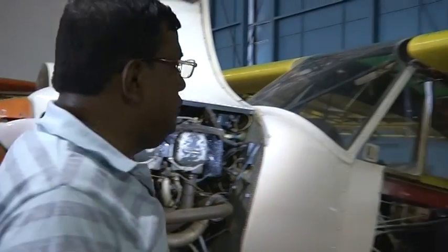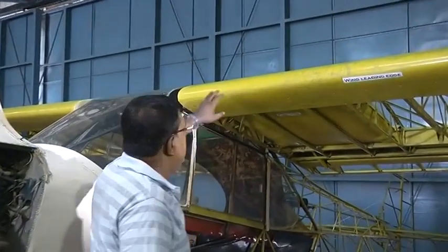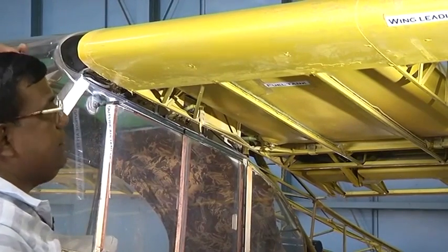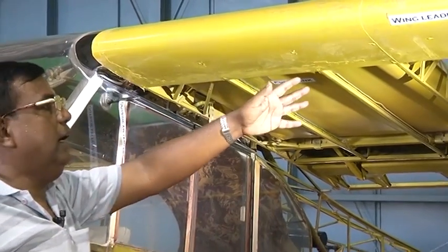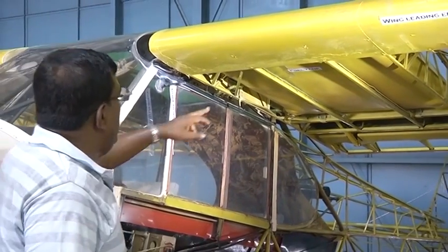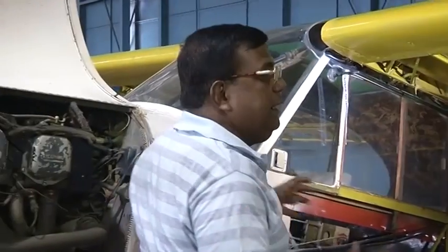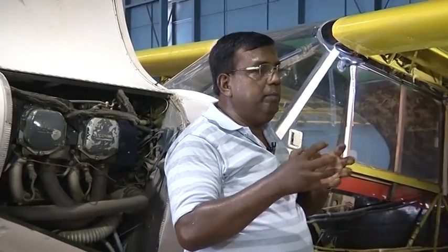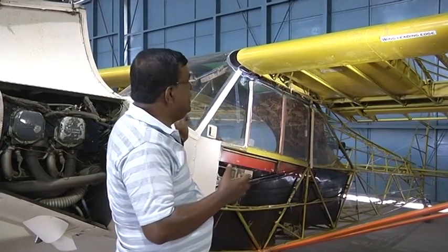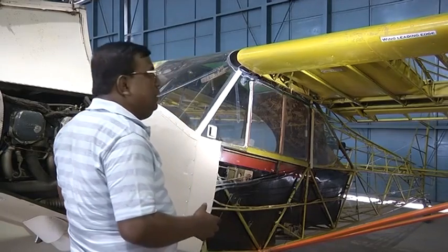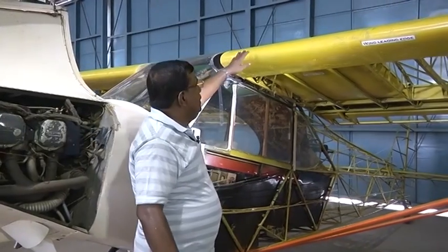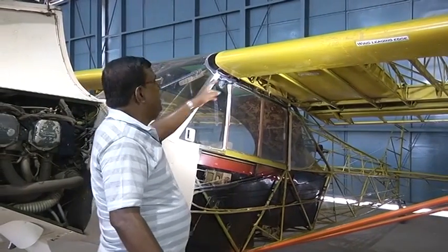In most aircraft, you will find the fuel tank is in the wing. Here is the fuel tank. You could see one fuel tank here, one fuel tank that side. For a larger aircraft, there could be a larger number of fuel tanks. The most important part is, please understand that fuel has to go to the engine, and the engine has a driving pump that is used to pull the fuel and put it inside the engine. All engines will have their own driving pump, which we call the driving fuel pump. And since it's a high wing, the fuel from here to the engine comes by simple gravity drop.